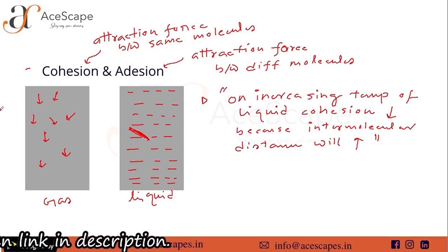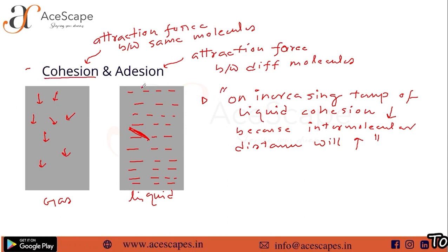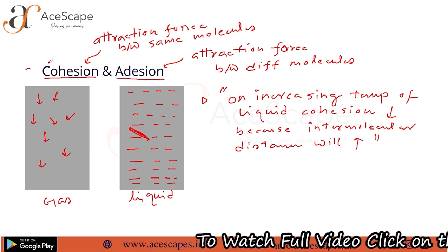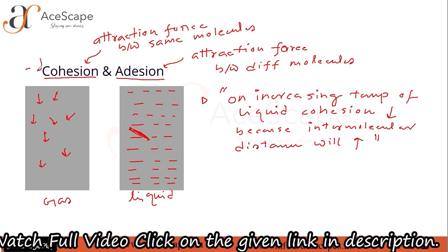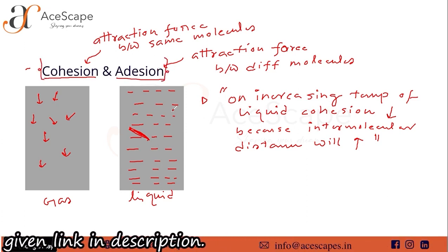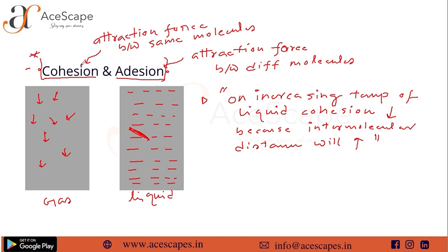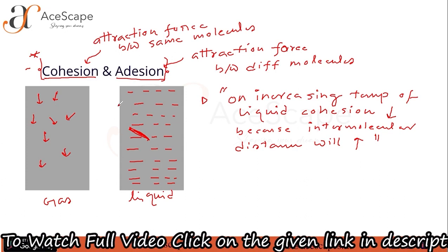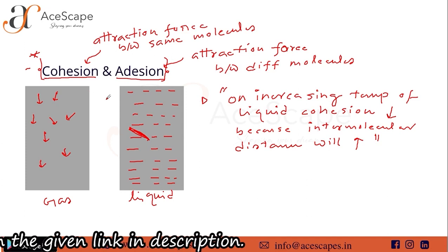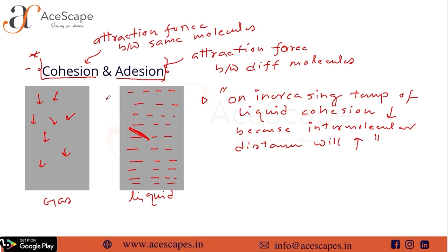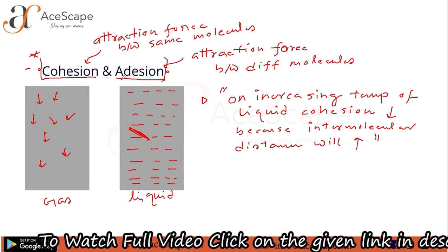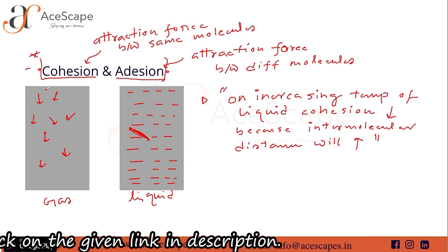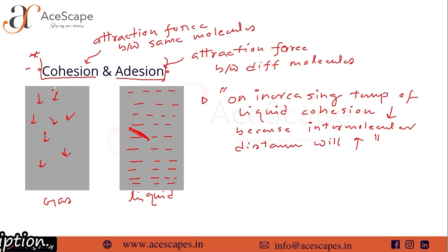So now you are thinking why sir is telling about this cohesion and adhesion. You will see in capillarity and surface tension. This is the major thing we have, brother. Remember, cohesion and adhesion is very important. So I'm not going to write it down, but I'm going to definitely tell you some observations about cohesion and adhesion. You write it down. Cohesion enables a liquid to resist tensile load, while adhesion enables it to stick to another surface.